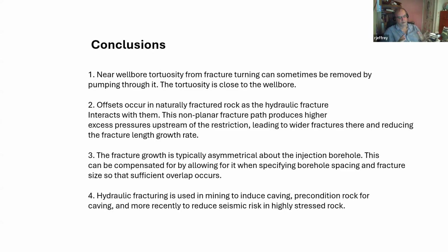And as the fracture grows through that, it sees initially one stress field that changes rapidly to the far field, and it rotates to always try to align itself to grow so that it's aligned with the maximum principal stress and opening against the minimum principal stress, and to minimize shearing at the tip.